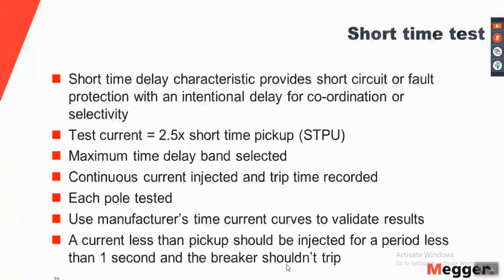Now let's look at the short time delay characteristics. Short time delay characteristics are provided for protection against short circuit or fault conditions, but an intentional delay is introduced here. Could be for coordination or for situations such as motor starting, where the motor can draw high current for a few cycles in the beginning.